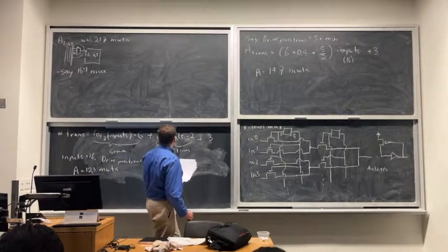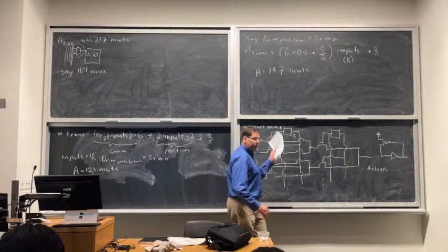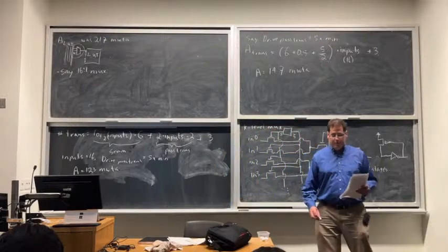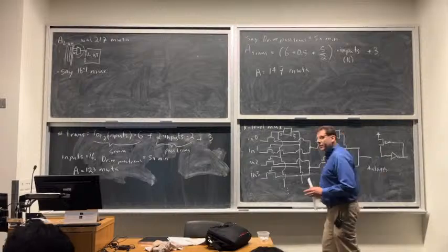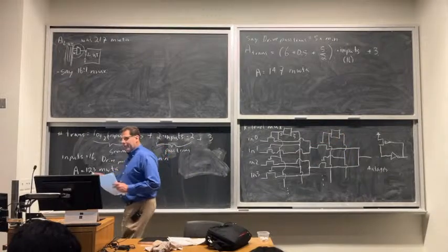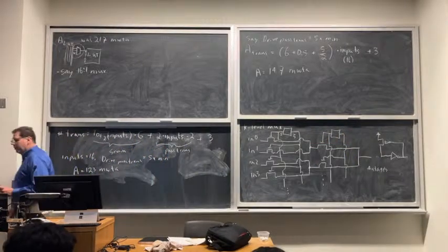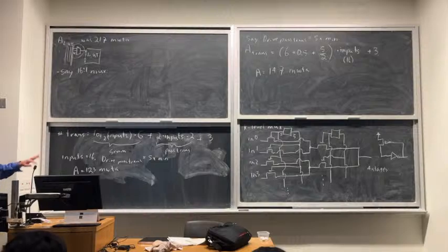So it's a reasonable savings. We went from 147 down to 123. So we save maybe, I don't know, 15 or 20% of the area. What do you think we did to speed? Is this going to be better or worse for speed than the one level structure we had at first? Yeah, it's going to be worse.